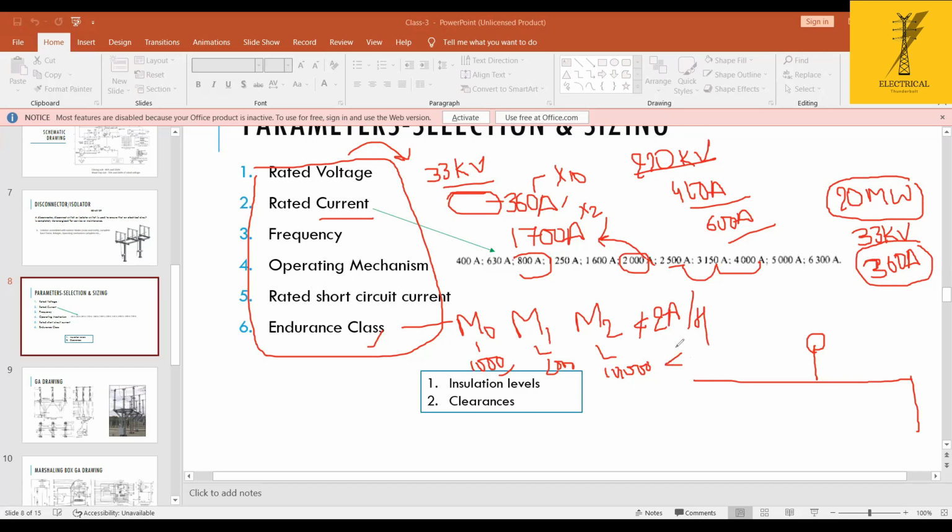And for all the aluminum contacts, it should not be less than 1 amp per square mm. And I am writing that my isolator should ensure the thermal withstand capability and wiping action during the closing or opening of the isolator, and all the tubes.